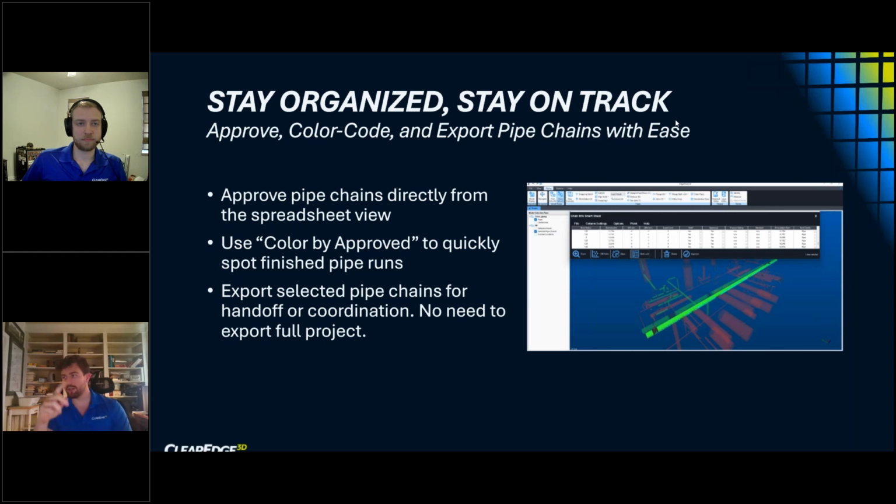As I go through, I can model my pipe runs, and I'll show this during the demo portion. I can then visually have an indicator of what pipe runs I've actually finished and modeled. And that works in with some of the older functionality like the export selection. So now we can visually track which ones we finished and then get those exported out into our end application.